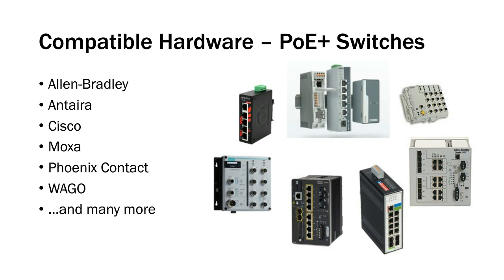So this short list here, there's no bias towards any of these. It's just an alphabetical listing of a handful of name brand switch manufacturers that I was able to quickly find who offer PoE Plus ports on their switches and injector products. And that includes both switches that have RJ45 ports as well as M12. You can see a couple of pictures in here are M12 connectors for switches that you might want to house outside the control panel.